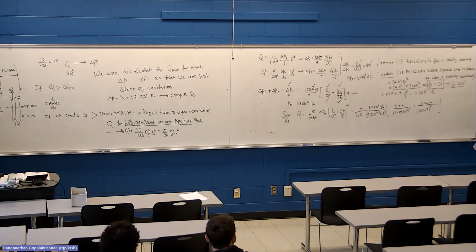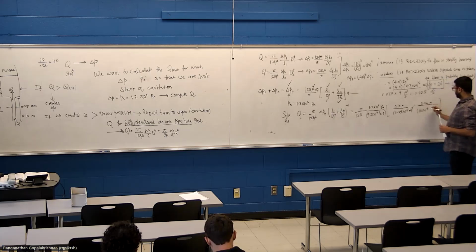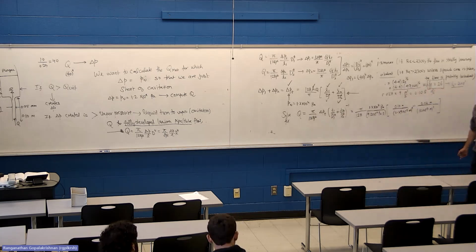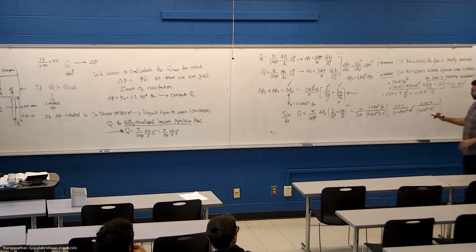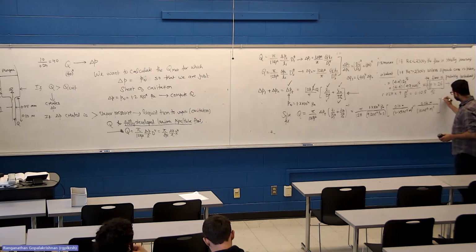You should also keep an eye on the units. So this would be meters to the fourth power. In the end, Q should have units of meter cubed per second. That's a consistency check. Do we invert that whole bracket? Invert the whole thing.